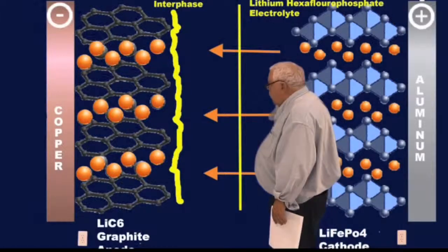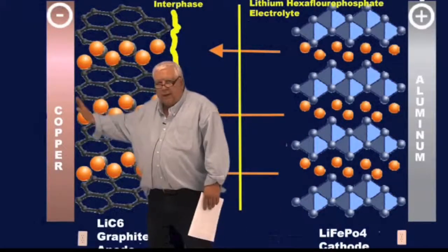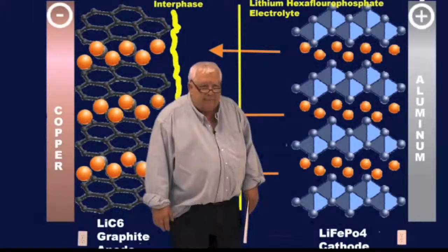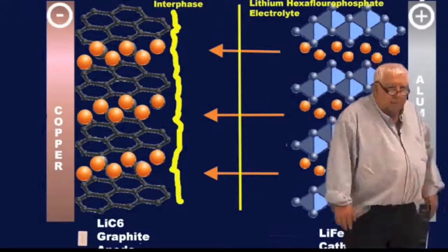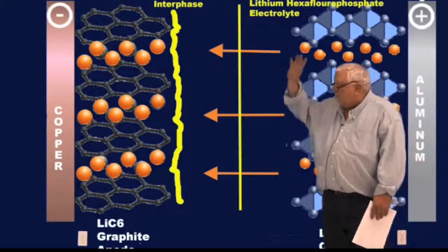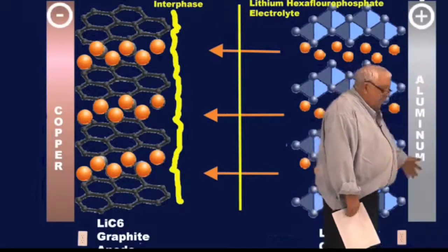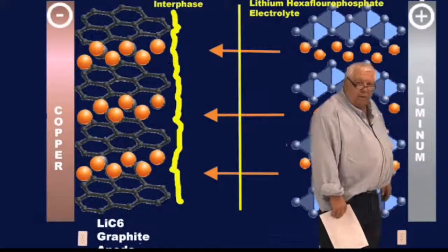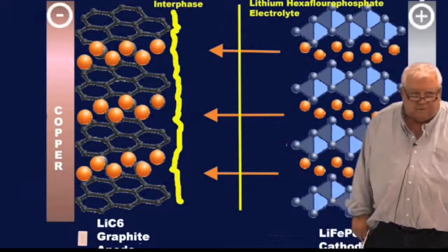This is the point where we create lithium ions, and it's the point where we create the solid electrolyte interphase layer. And once we have our anode fully lithiated, and we have removed all or most of the lithium from the phosphate cell, we're said to be fully charged.